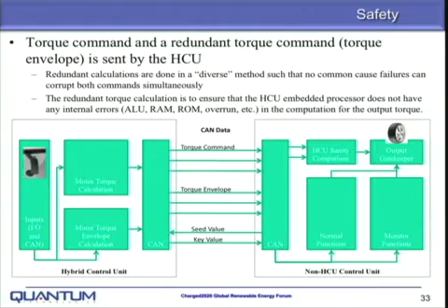So last couple slides here then, there's a couple ways to essentially secure your torque. You supervise, let's say this is your hybrid control unit over here, that's basically taking the input from the pedal, and you got redundant sensors in the pedal. That's one of the first things you do. And you calculate what's called a diverse software. You calculate things in a diverse way. So you're calculating essentially the same thing in multiple different ways such that you don't have a common cause failure.